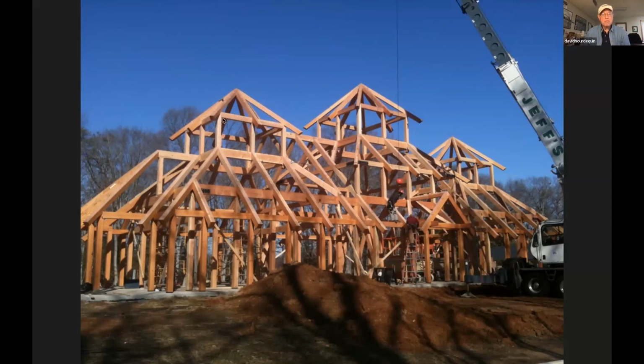So you go from the tension ring, and then you've got these posts in here. Now this gets laterally stabilized later. Don't worry about the racking. That was all done with shear walls. So you come down here, and now we've got another plate line around here. Well, with the loads on that now is a compression ring. You know, you're pushing up on it, and so it kind of works in reverse.